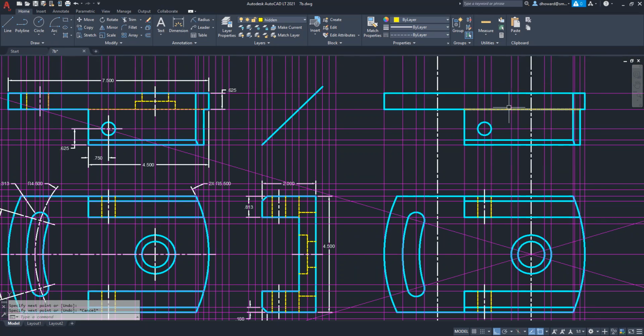So if it was just a straight hole, we'd have these two lines, but because it's a counterbore, we've got to show the part that goes in a ways, as you can see here. I'm going to need that offset. That offset thickness, or the depth of the counterbore, is 5/16. So let's offset that line. So this guy down 5/16.